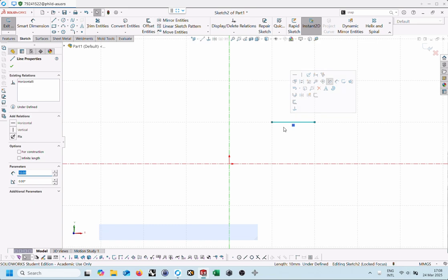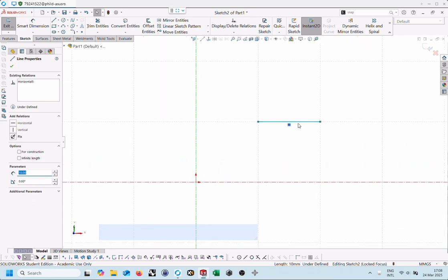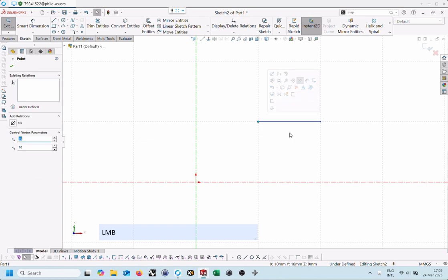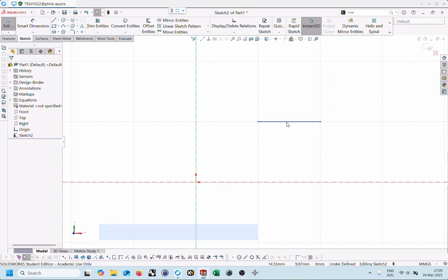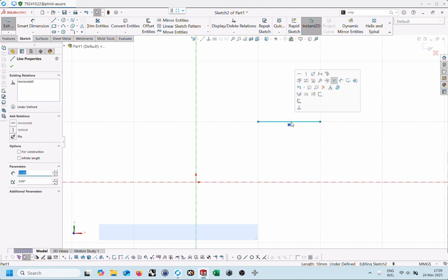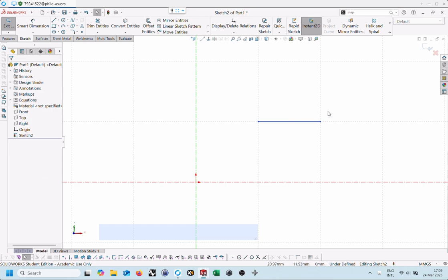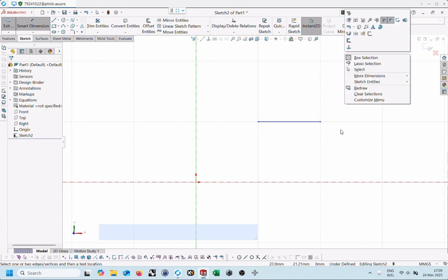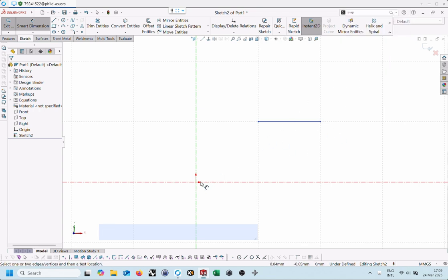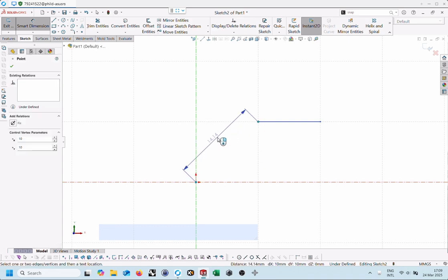Now the thing about lines, and arcs and all sorts of things, is that they usually have at least 2 endpoints. So that's an endpoint, and that's an endpoint. And then there's a midpoint in here as well. If you want to start dimensioning, it won't activate now because I need other dimensions before I can do that. So let's position this dimension. Remember, position is going from the origin up to that point. And that useless dimension is not going to help us.